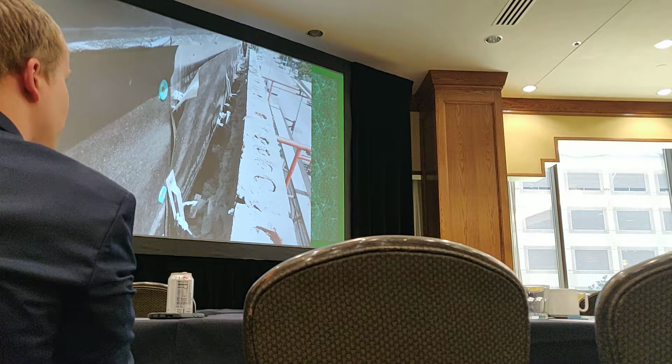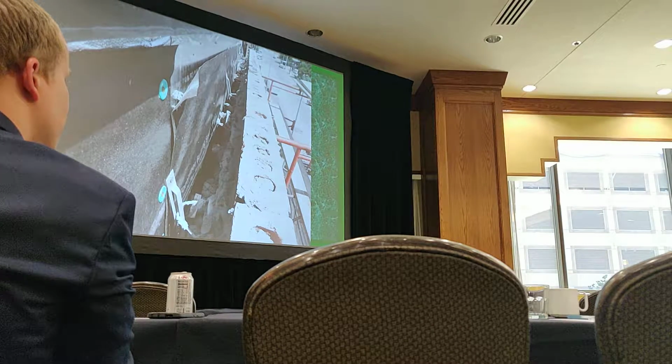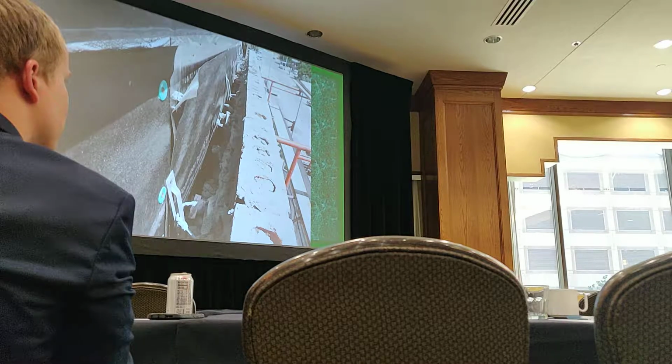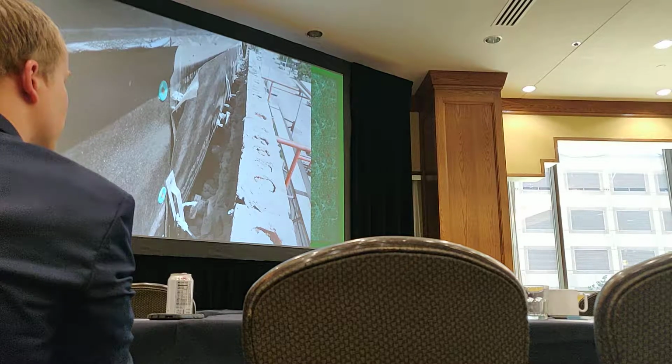And then this one's a little harder to see. This is the attachment to the backing. This one is also in downtown Austin, different site. Wood frame construction, which is commonly going to have those corrugated ties. We actually have a 2-piece anchor, so we thought everything was going to be fine, except they were attached with a single roofing nail, only at the top.